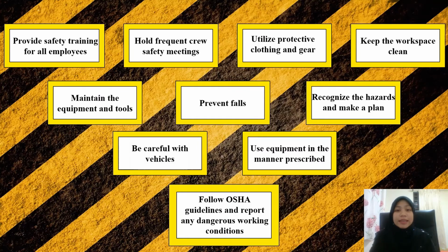The other way is prevent falls. It is important that workers are protected from falls on the job. The installation of fall protection systems can protect construction workers. This system should consist of such items as guardrails, toe boards, screens, canopy structures, or nets. Scaffolding can prevent falls, but must be installed properly to make sure it is constructed well enough and must be inspected regularly.